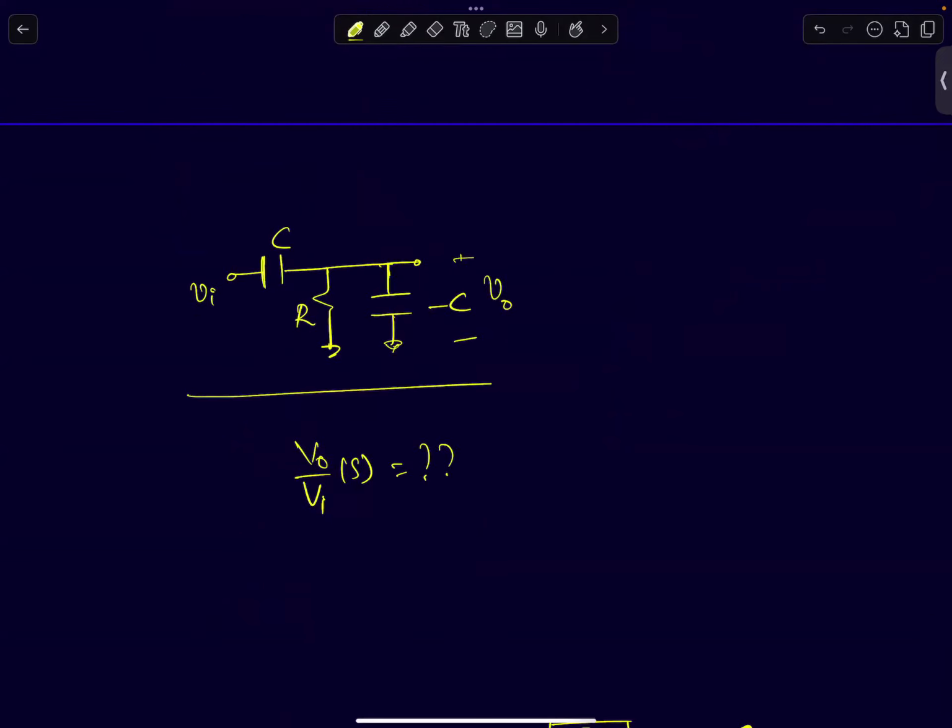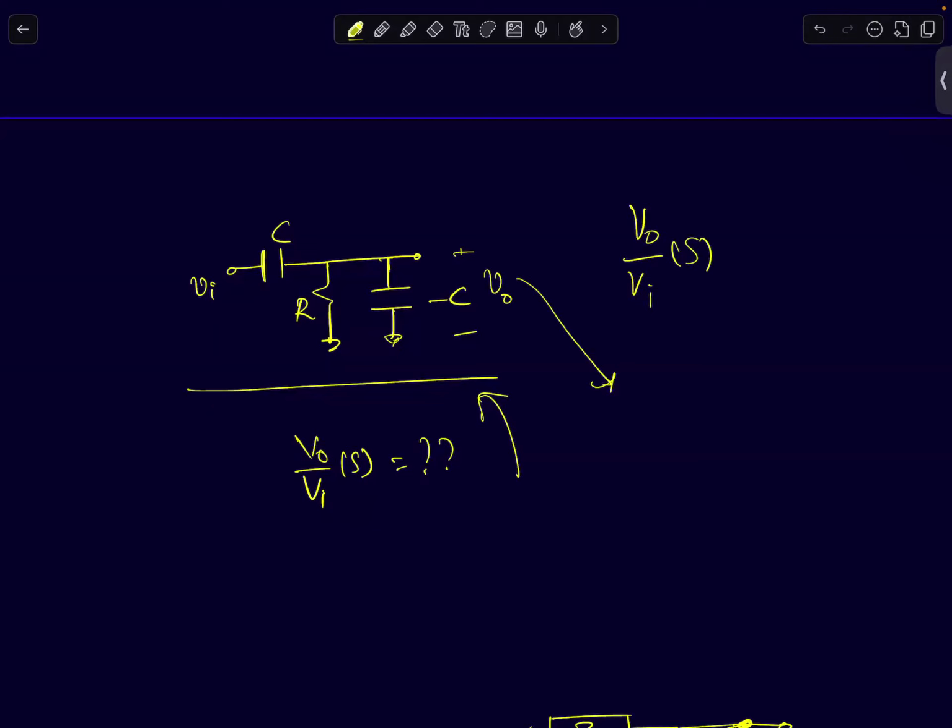Now, let's say we start with, we'll just interchange the capacitors and resistors. If you do that, now can you guess what will be the transfer function? You can apply the same source transformation theorems. The same source transformation theorems will hold here too. Can you tell me what will be V0 by Vi for this circuit? Apply the similar source transformation theorems. This is a voltage source of value Vi, convert it to a current source. That will be Vi by 1 by SC. So it will be SC into Vi, right?